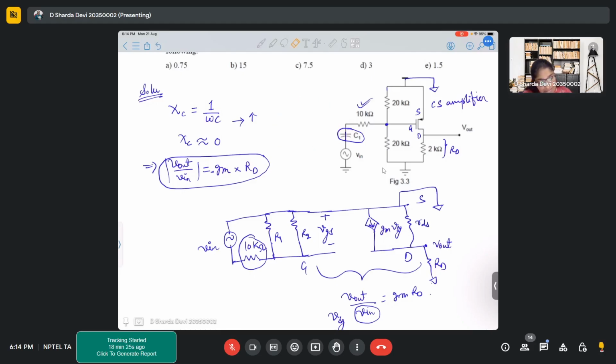So here, let's say if this 10 kilo ohm resistor was not present, it would have been a short circuit, right? So your Vin would have actually appeared across your R1, R2 as well as your VGS or VSG, right? Is this clear to everyone? When I say this 10 kilo ohms resistor is not present, the voltage appearing across your VSG will be Vin. Is this clear to everyone? Because they are simply in parallel, right?